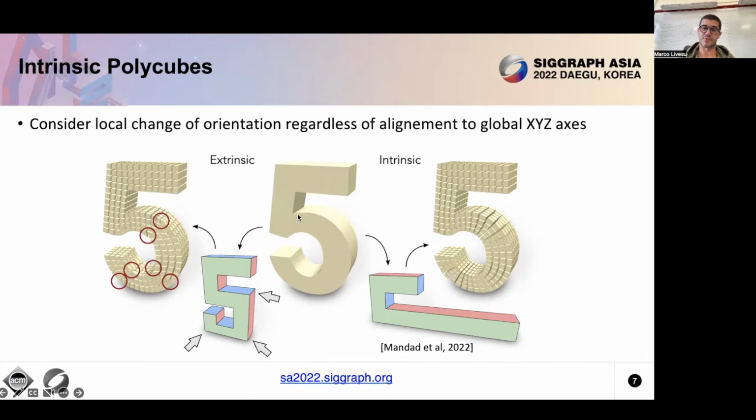The problem with these approaches is that when you have a shape like this, which is nice and round, but is just changing orientation with respect to the global axis, you tend to split the structure in polycube space, introducing new elements in the polycube, for example, these corners pointed by the arrows. And the polycube corners are going to define singularities in the hexahedral mesh, which are completely misaligned with your shape and introduce elements of poorer quality because they are not geometrically needed, in a sense.